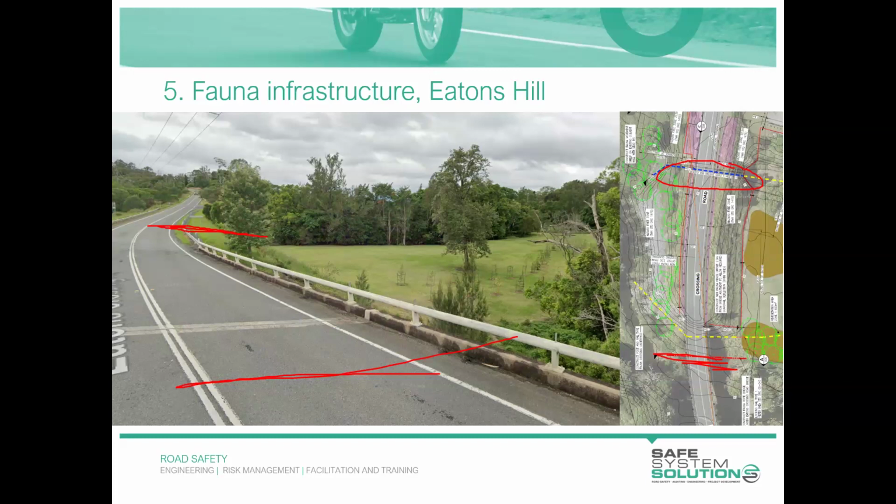The other risk is that a worker gets hit by a vehicle, and this falls under the category of exposure in the vicinity of the workplace. The initial likelihood was unlikely, but the impact was catastrophic, which gave us an extreme risk rating for this risk. The control measures suggested are to reduce the speed limits to 40 kilometers under temporary traffic management, and potentially move traffic away from the work zone, which reduced our risk to a low risk rating.